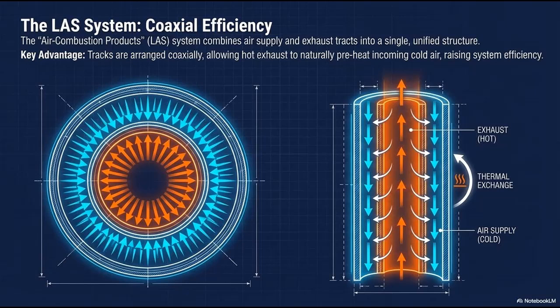that sealed house. And the boiler is just relying on the passive, natural upward draft of a hot chimney, while the kitchen hood has a high-speed electric motor. The kitchen hood is going to win that fight every single time. It will. And when the boiler loses that tug-of-war, it begins to suffocate. Yeah. This is where the physics turn deadly.